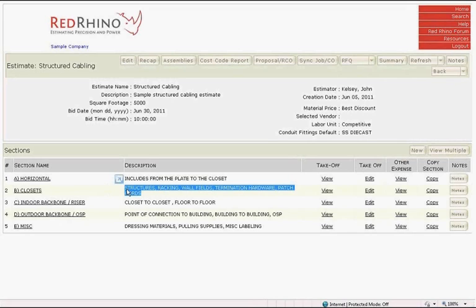Next is section B, closet. Closet includes structures, racking, wall fields, termination hardware, and patch cords. Structures cover your racks, cabinets, and wall swing cabinets. Racks may be 2-post or 4-post on a raised floor or concrete floor. Overhead racking can include wire baskets or standard Telco ladder racks.